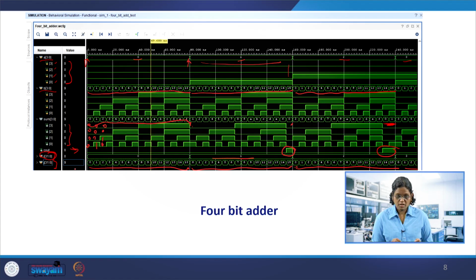So this is a 4-bit adder. Actually, this is taking the previous bit carry and then proceeding into the next bit and so on. To get the final bit sum and carry, it takes time. So when we do the timing analysis of this 4-bit adder, we can discuss the timing details of this adder. Right now we have this as a combinational circuit with the data flow model, and the wire which is declared in between gives the structural model.